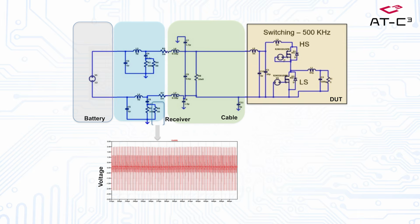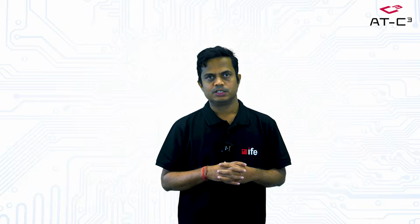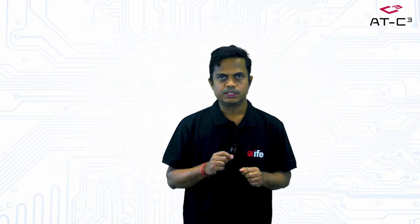As we have talked before, this is a buck converter. It has multiple switches, high side and low side, and the switching noise travels from the buck converter through the harness to other devices or the battery. In this case, we can see the switching event happening and the noise in the diagram. So our aim is to suppress this noise, and hence we need a filter.